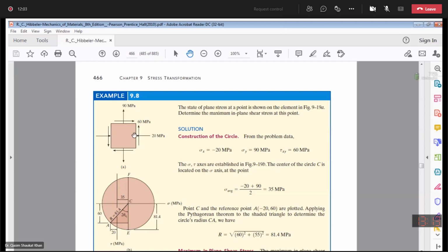Now we are going to repeat the same data and draw the Mohr circle. In the Mohr circle, we will calculate principal stresses, maximum inclined shear stresses, orientation of the principal planes, and orientation of the shear planes. Then we will also calculate transformed normal and shear stresses.